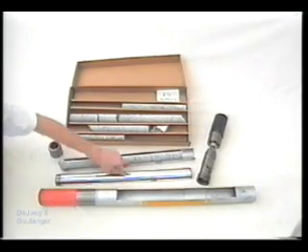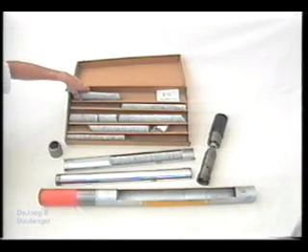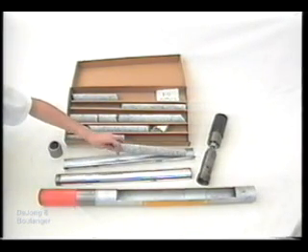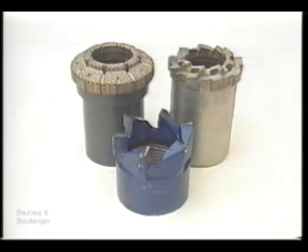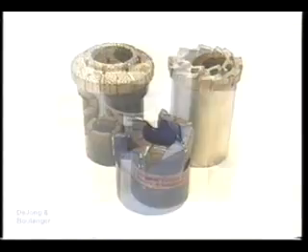The sample is measured, identified, and stored in core boxes. After reassembly, the core barrel is lowered to the bottom of the hole and drilling and sampling are continued. Coring drill bits come in three basic types. Pictured from left to right are the diamond, carbide, and sawtooth.